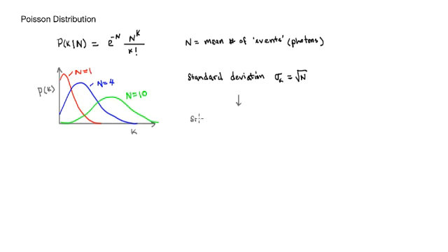Okay, now we can look at an important property, which is the ratio of the signal in the imager divided by the noise. The signal is going to be n, because if you measure on average n photons, and the noise is the square root of n, as we just saw. So this ratio goes like the square root of n. This is the signal to noise ratio, SNR, which is a very important parameter. What you see is that if you have more photons, the signal to noise ratio gets bigger, so the image will be less noisy for more photons.